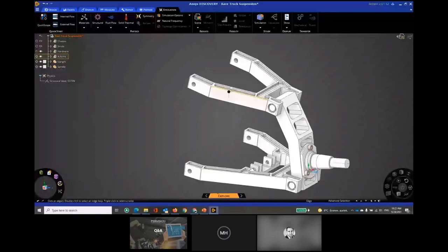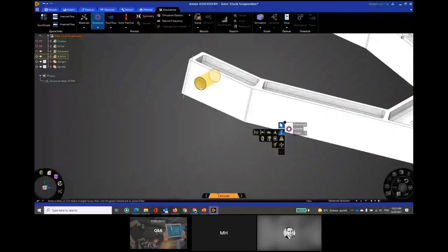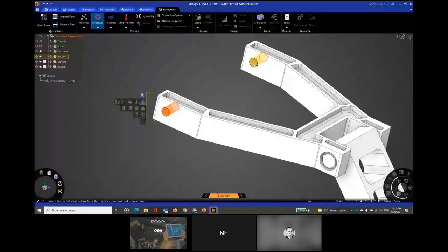Well, of the user interface components, I have one more in here in the middle of the screen, this hexagonal one. If you click that, you can decide what you want to do. I want to go for structural simulation. I want to go for supports. Let's click that one. Then this heads-up display is now giving me the possibility of just starting to make constraints. I'm holding my control key to have a multi-select. And instead of making it a fixed constraint, I'm willing to make it a hinge. So basically this is now able to rotate around. I will accept or hit enter.